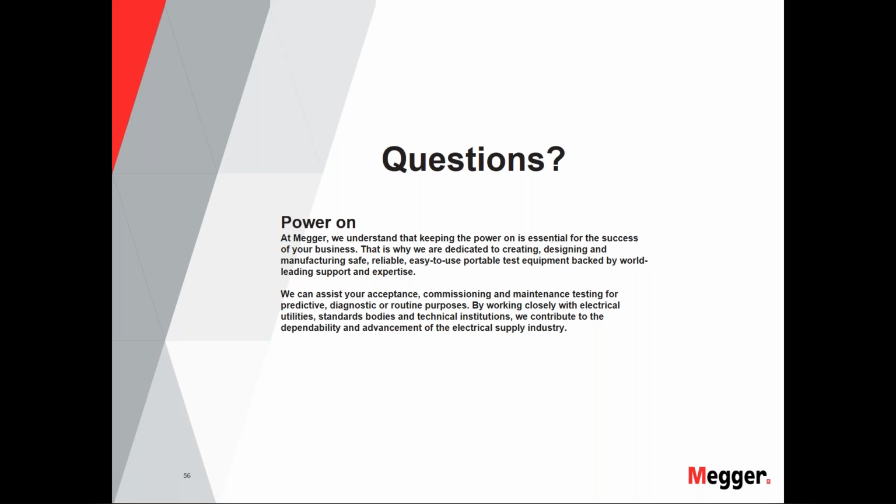Hi, good morning all. In general, the 32 element is used to protect against prime mover loss of power. When we are in synchronized condition and the prime mover starts losing power, basically it's not able to pull at speed. Then the generator starts drawing current from the system. So the answer to this question is it's the current. We see the reverse direction of the current, and we calculate the reverse power to operate the element.